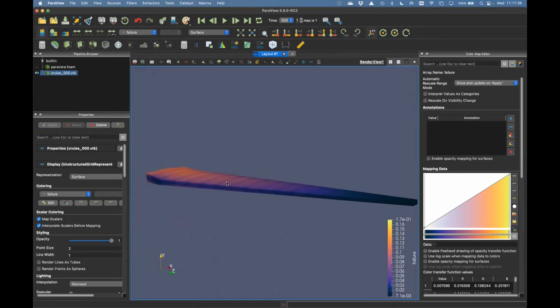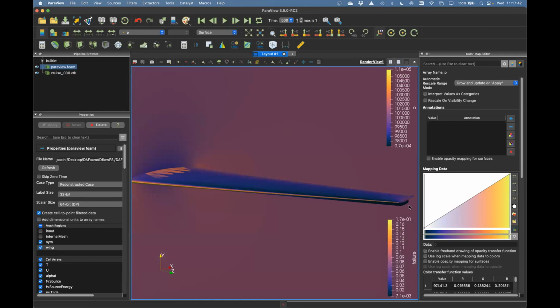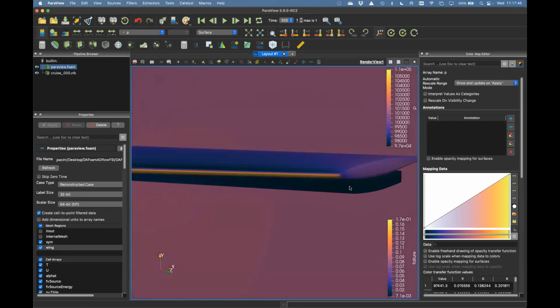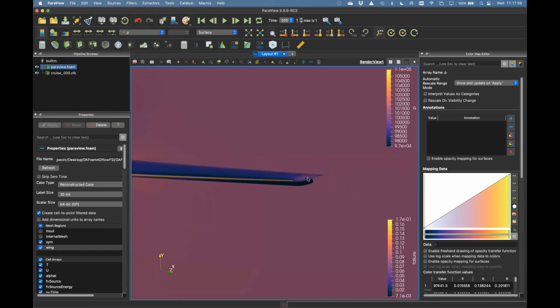Now, in ParaView, when you show the aerodynamic mesh, you'll see that there's a discrepancy between the mesh from the aerosolver and the structural mesh. And this is because the aerosolver is given these updated coordinates and the mesh is deformed. So the aerodynamic mesh that you see on top is a true deformed mesh. The structural solver is just the baseline design without any displacement.